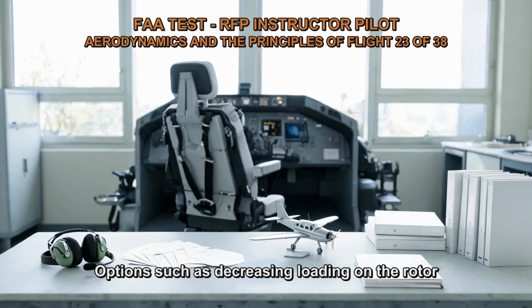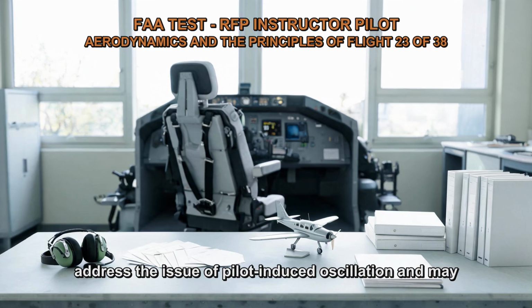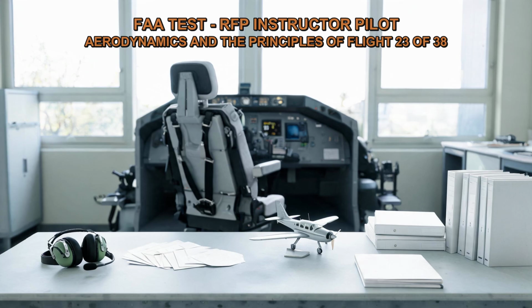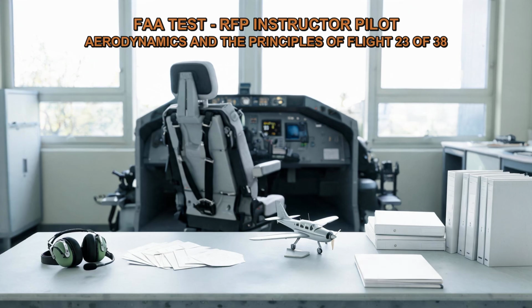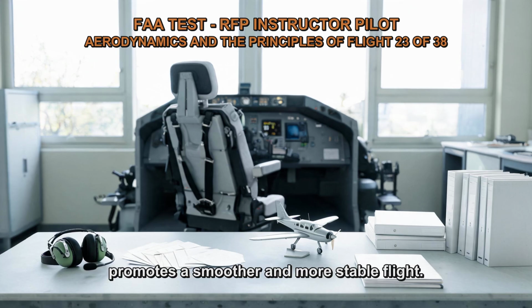Options such as decreasing loading on the rotor blades or raising the center of thrust above the center of fuselage drag may not directly address the issue of pilot-induced oscillation and may have other effects on the aircraft's performance. Therefore, adding a horizontal point of reference is a recommended approach to help prevent pilot-induced oscillation in a gyroplane. It enhances pilot awareness, improves control precision, and promotes a smoother and more stable flight.